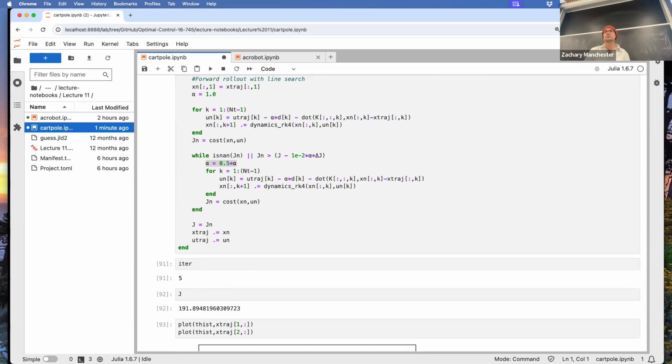Anybody else? Yeah. We do a similar thing in homework with LQR. Is the advantage of this that you don't need a reference trajectory? This is generating the reference trajectory. So in fact, this gives you the reference trajectory. It also gives you the LQR tracking controller for free because those Ks that come out of here are the LQR controller. So if you just run this, you not only get the reference trajectory at the end, you also get the LQR tracking controller, which is kind of cool and kind of useful. In fact, that's quite useful if you're doing this online, because you can run this thing at like 10 hertz, say. You can use the LQR controller and run a tracking controller at like 1000 hertz if you want to in between these solves. It's actually kind of useful. There are cool things you can do with that.